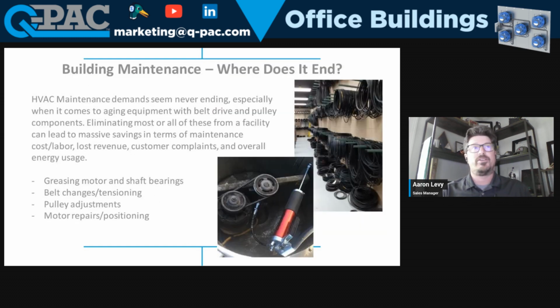Next one for me. And a lot of the maintenance, we always say, where does it end? When you're looking at a lot of old existing systems with belt drives, direct drive plenum fans, vane axials, things like that, where they've got direct drive motors or belts or pulleys, there's always some kind of servicing that needs to be done: bearings to be greased, belts to be changed, motor tension bases need to be adjusted on a regular basis. These things eat up a lot of maintenance time.